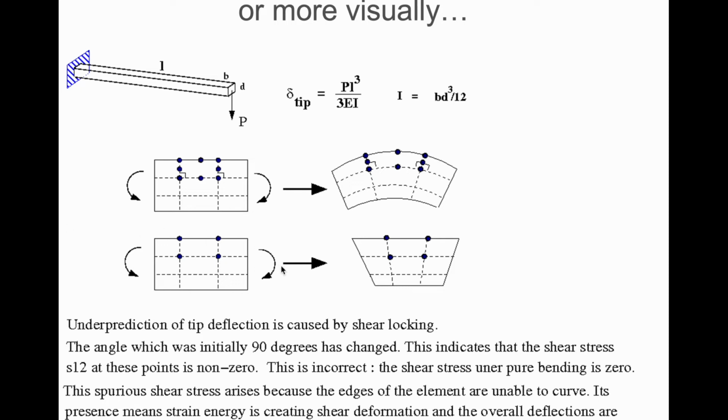So translating this into something more meaningful for you, we can have a comparison between the shear. So we have a pure bending here, but we can check what happened with a linear element and a quadratic element. When you have pure bending, you can see that the quadratic element can reproduce well the curvature, but with the linear element, because of the natural linearity of this kind of elements, we cannot have here a curve, so we are not going to fulfill the condition.